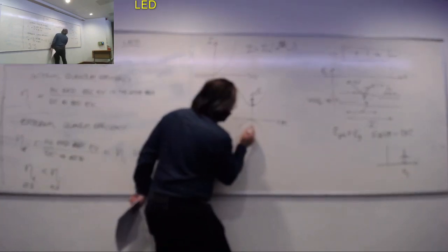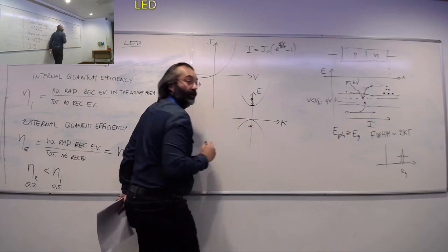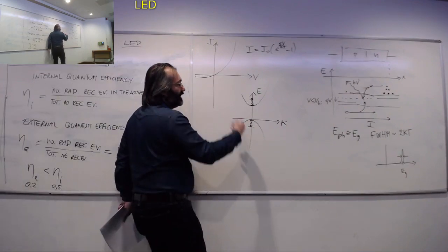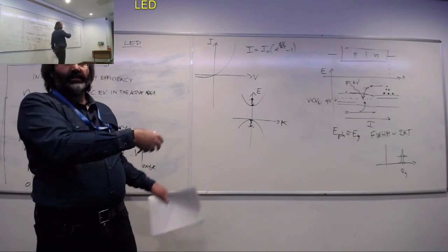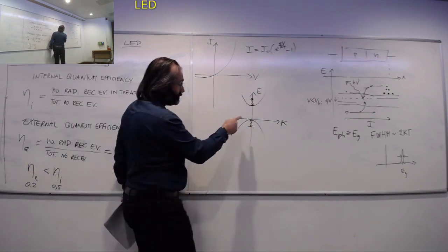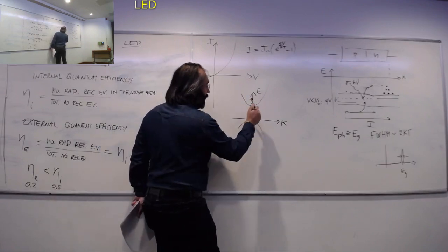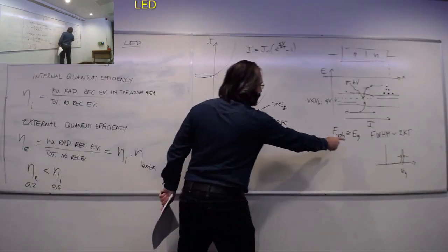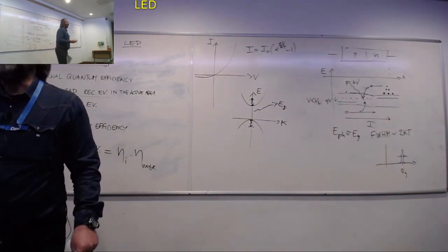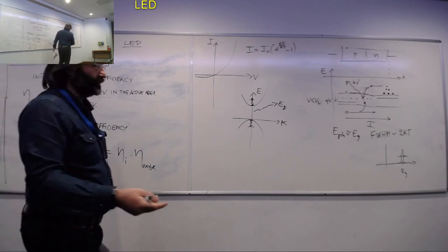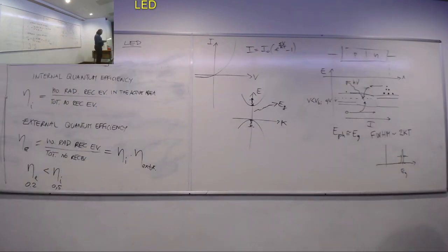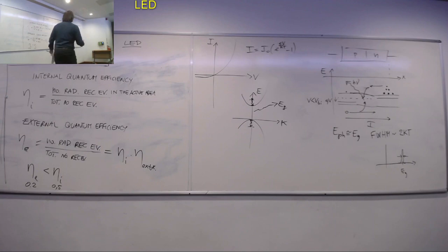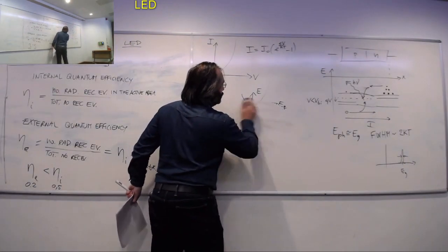The same here: when the electron has been promoted, a hole is left behind. The hole as well will thermalize. So in the end, the electron-hole pairs that were left behind after the electron was promoted always end up there. And so when they recombine, the energy is always roughly Eg. So that's the reason why in light emission we have a spectrum of photons that is always around Eg. So this is really briefly the fundamental stuff about my LED.